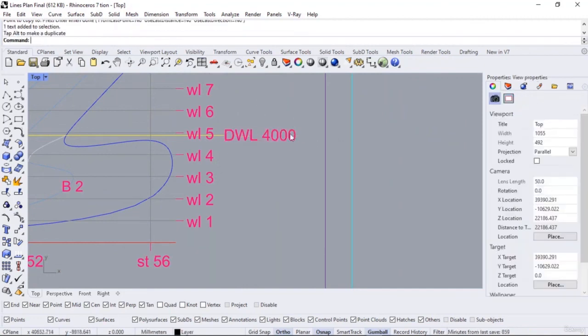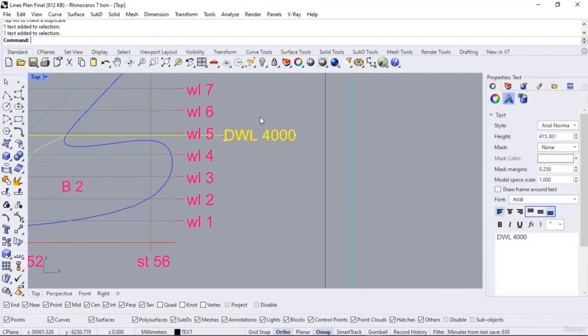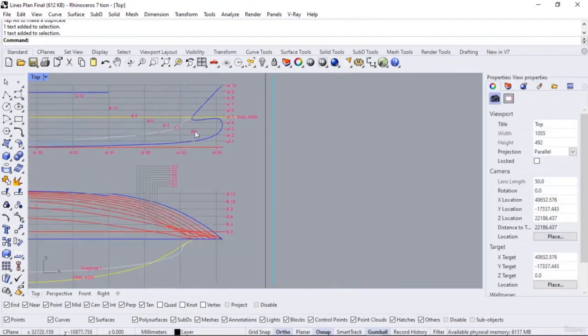If the gumball of the object you have selected is not visible, you should open the gumball from the bottom. Gumball is not visible when the gumball option here is not turned on. When we click it, gumball is no longer visible, but when we turn it on, gumball is displayed again. This is how you can turn gumball off and on.